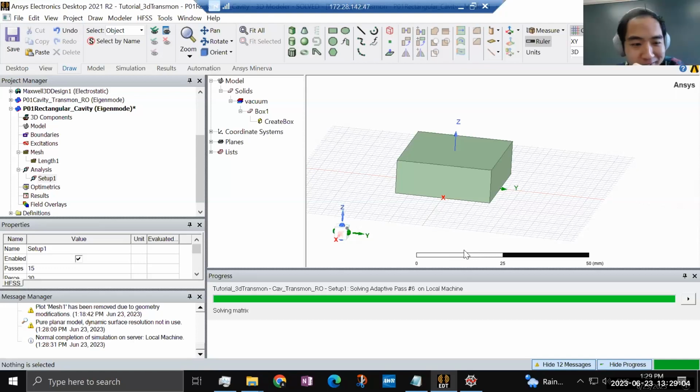Good question. We can import from external sources, like you can import a GDS file into HFSS, for example. I don't know how you can import a 3D CAD design, but I think the parameterization doesn't work when you import. When you import an object, it's basically one whole object defined like a point-wise feature.